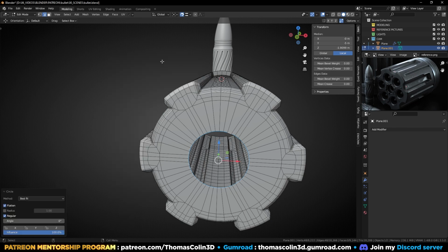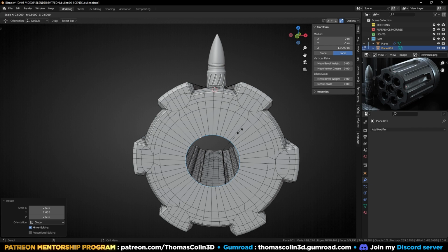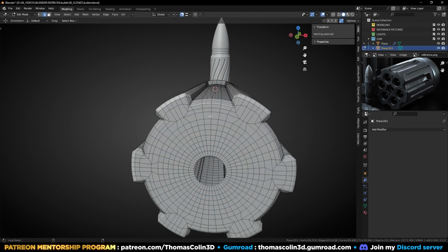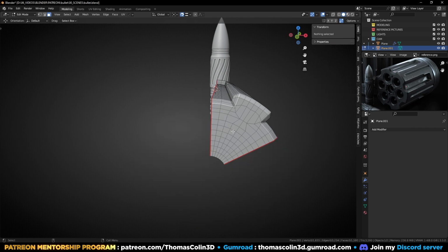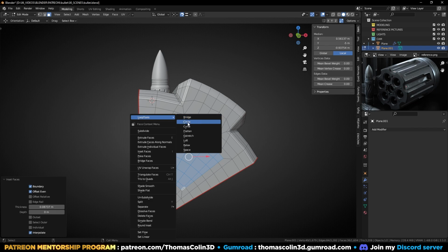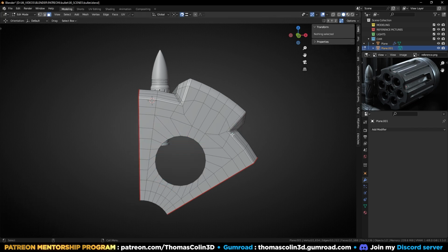Right-click, loop tools, circle. Scale it. E, S. Add, let's say, 6 loops. Select this edge loop and this one. Right-click, mark seam. Now I can just select one polygon, L. Invert the selection by pressing Ctrl I and delete. Select these faces, I. Right-click, loop tools, circle. Scale. Remove the polygons.